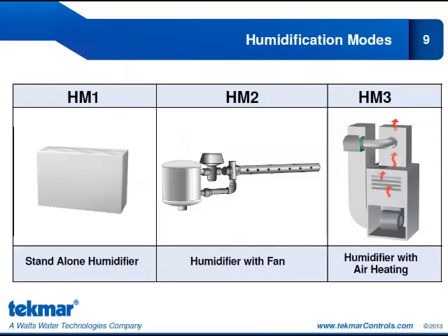Humidification mode 2 is a humidifier that will require a fan for operation. And an example of this, as shown on the slide, is a steam injection humidifier, where water is boiled and steam is injected into the duct. Now, we do need that fan to carry the moisture in the air to the space.